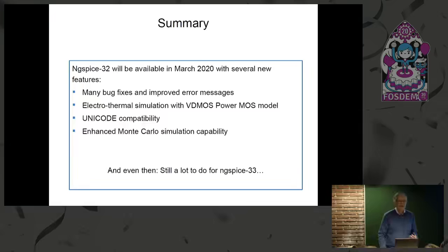Not yet. It's just a matter of this interface between KiCad and ngspice. ngspice, in fact, does calculate voltages. And then you could tell, of course, that the output graph is not a voltage, it's a temperature, because the equivalence is clear, and the relationship between these two is clear. So ngspice calculates voltage, but in fact it's the temperature, and the graph should show temperature. Within ngspice directly, you can just tell it, this is not a voltage, this is a temperature.